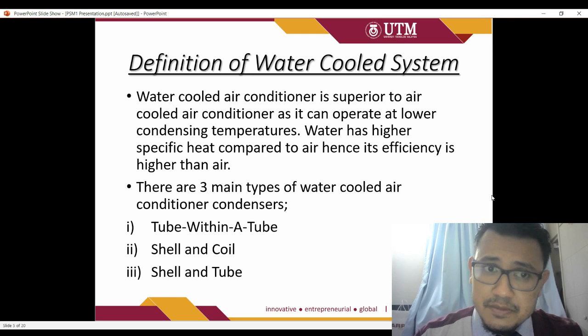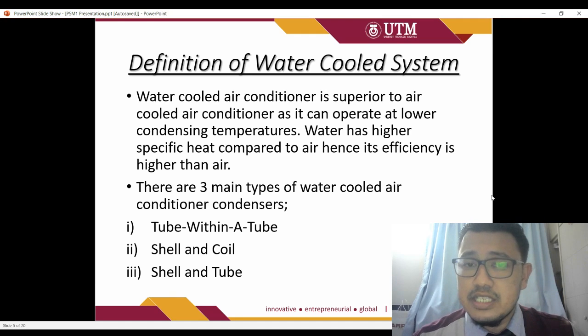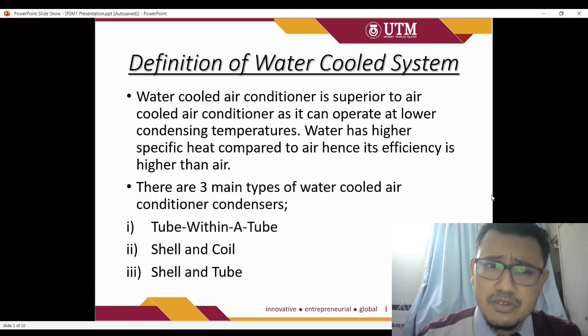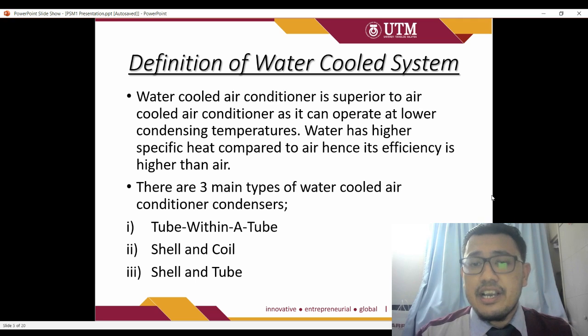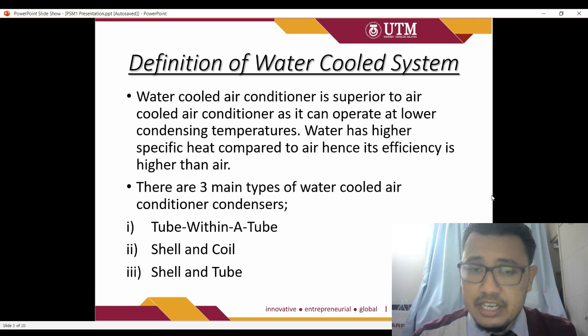The definition of the water cool system: water cool is an air conditioner that is superior to the air cool air conditioner, operating at a lower condensing temperature. Water has a higher specific heat compared to air, so the efficiency is higher than air.